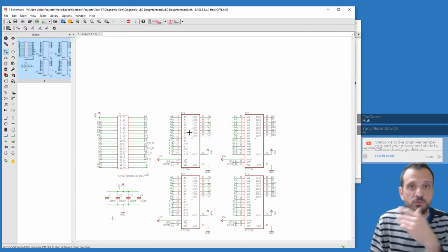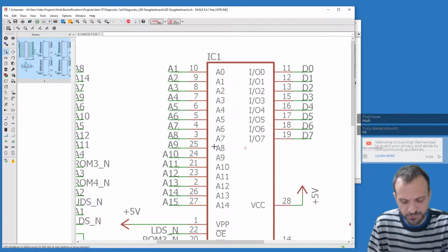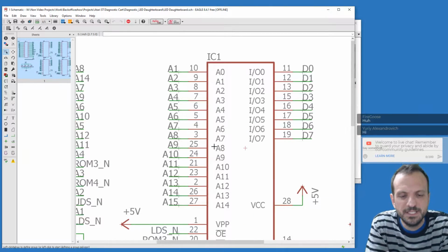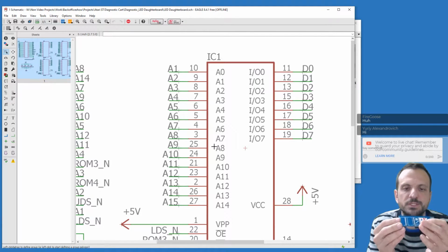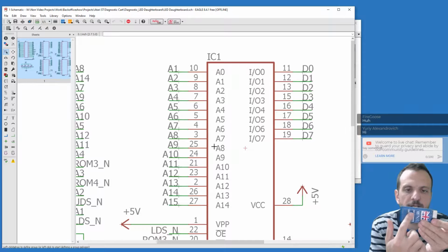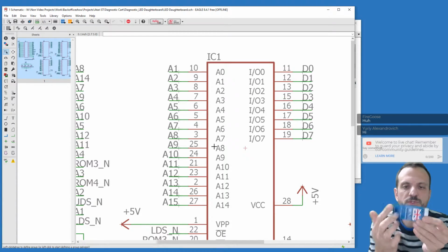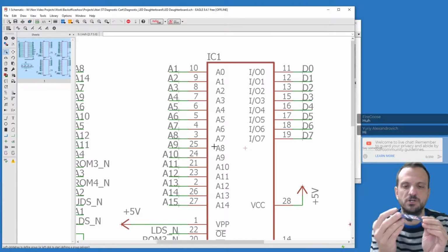So what we need to do when we do that is design the pins appropriately. Maybe we might even have 2 versions. Let's have a little think. I guess you'd have to decide how you want to do it. For me, I think I would put a socket on the top, possibly on both, and then have a daughter board that maybe even sits on top. There's a lot we can do.